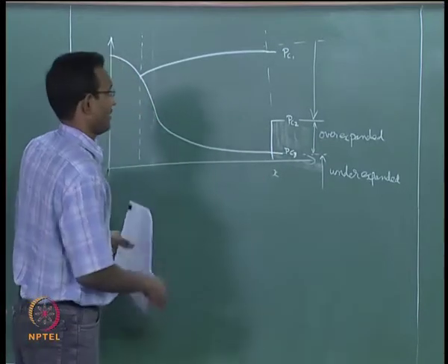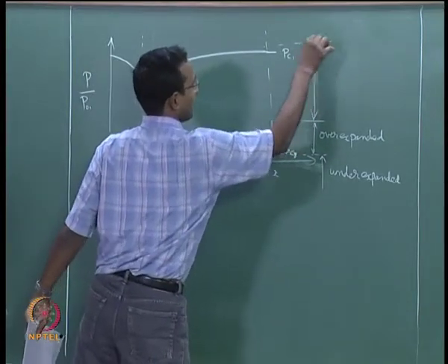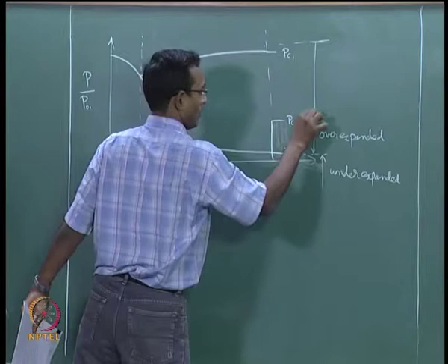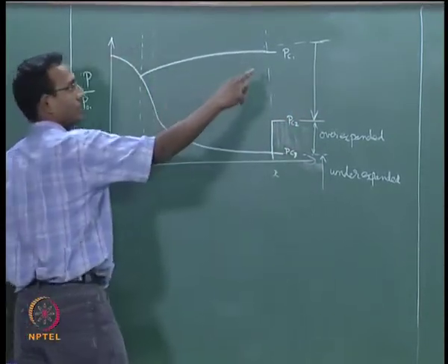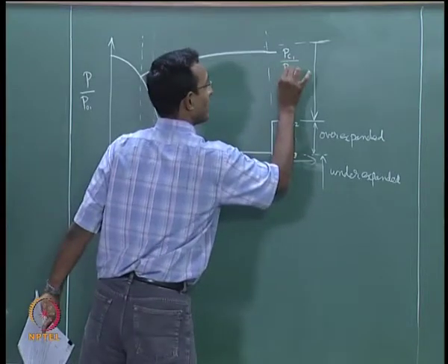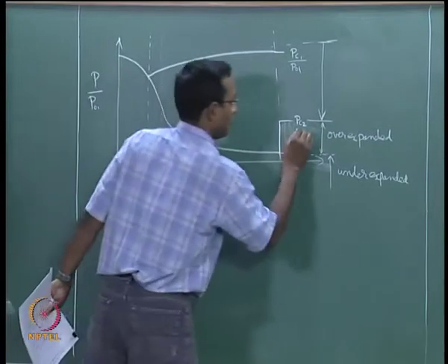So from Pb equal to P01 till Pb equal to P critical 2, everywhere this is what is happening. Oh, I am confusing here, it should be P critical 1 divided by P01 here, because I am plotting P by P01 as my axis. It should be non-dimensionalized everywhere.